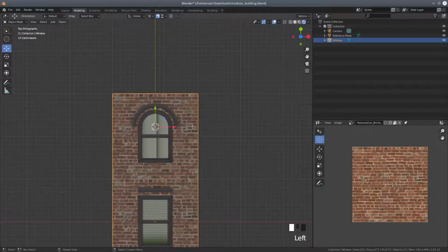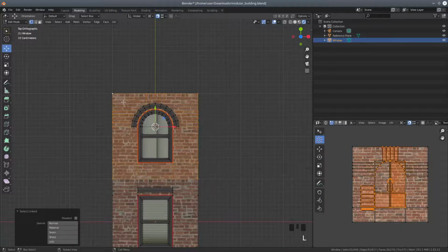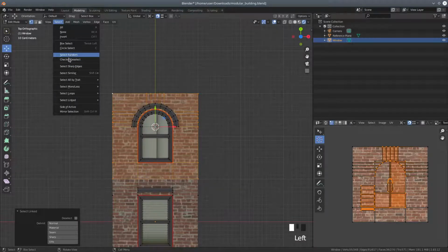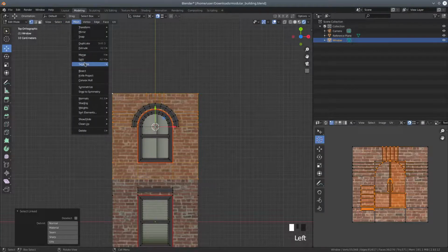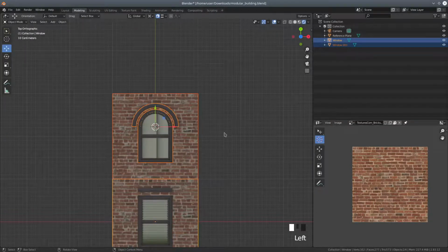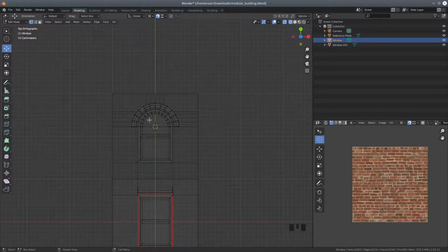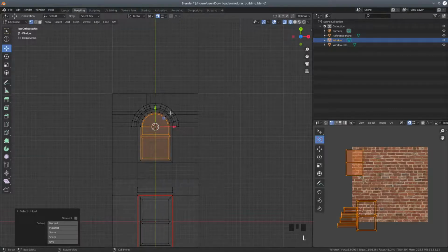Could be because we've got an odd scale. Yeah. Okay. I think if we select all this mesh, we need to separate that. So go to mesh, separate, selection. So that will turn it into its own object. That is probably okay. We also need to do this bit. So go into edit mode. We can press L and L. So L on that bit, L on this bit.